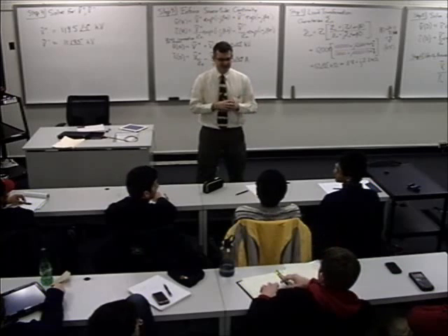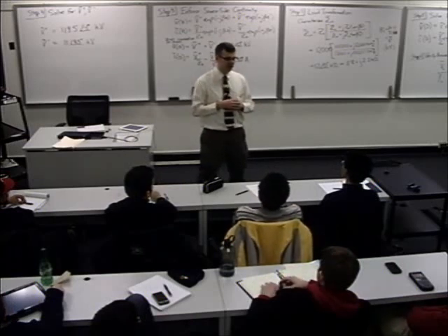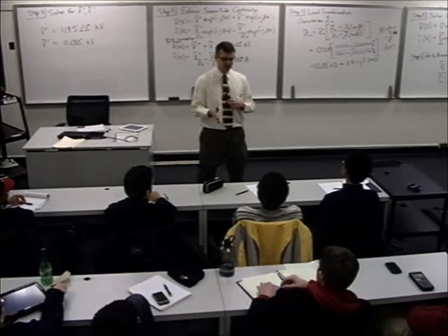You don't really have to worry about reflection coefficients when doing this analysis. We did it without reflection coefficients, but that's actually another way to double check your answer. Your V minus should be equal to your load reflection coefficient times V plus.